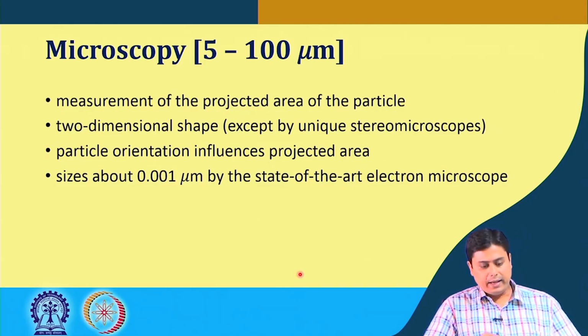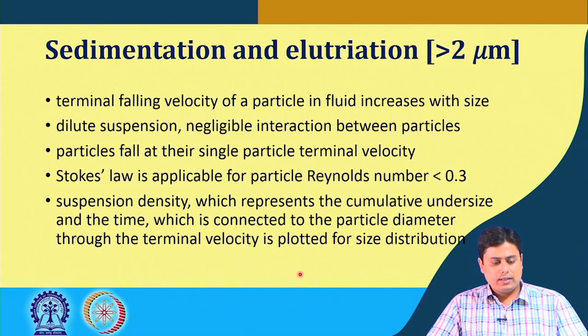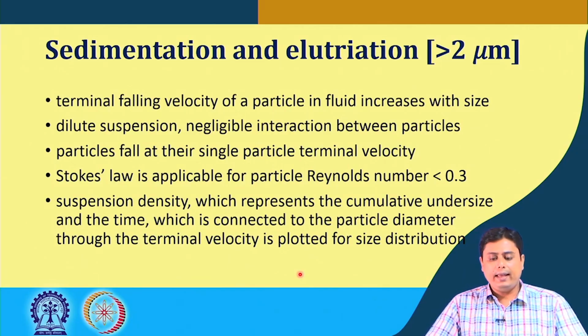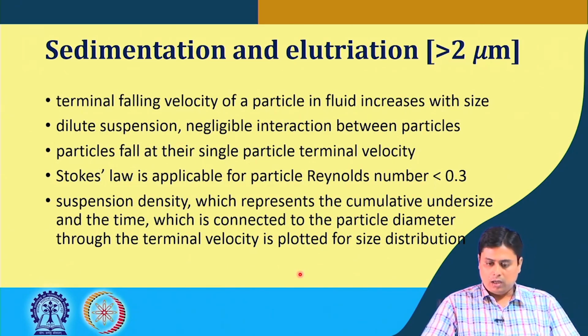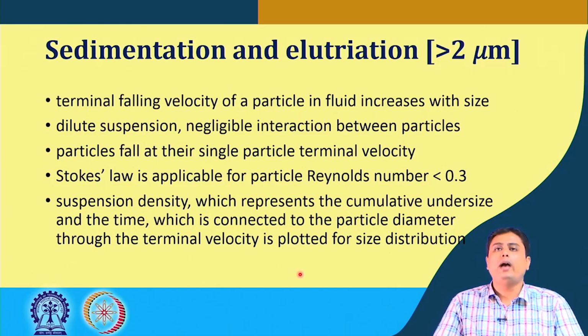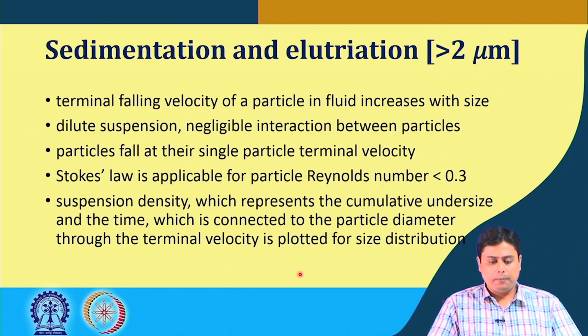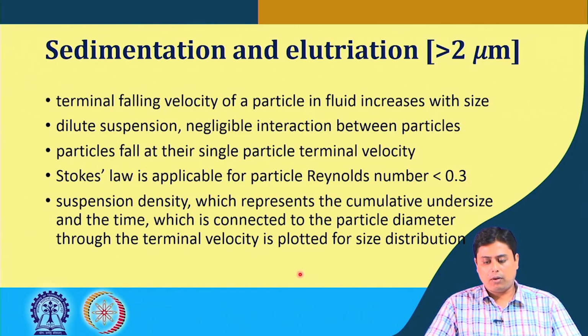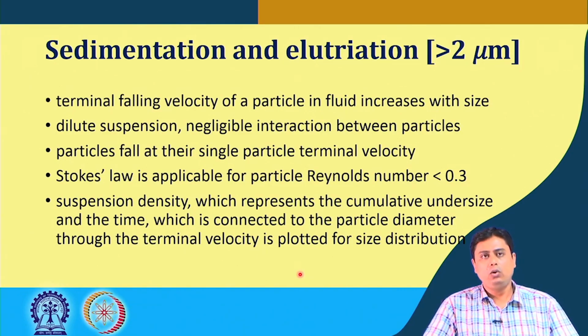The next technique I will discuss is sedimentation and elutriation, which helps us with particle size measurement for sizes typically greater than 2 micron. So, this technique is typically applied for particle sizes greater than 2 micron.